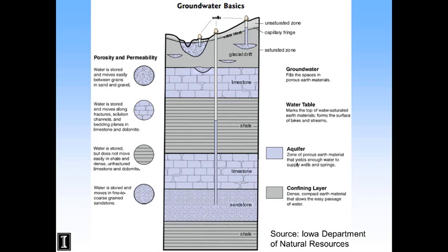But I know in Illinois, in the Chicago area, for instance, there are shallow sand and gravel wells in sand and gravel aquifers that you can tap for water supply, but the larger communities up there are actually drilling down 1,600 feet into a sandstone and limestone aquifer, the Mount Simon, for their large water supply because of the amount of water it will provide.